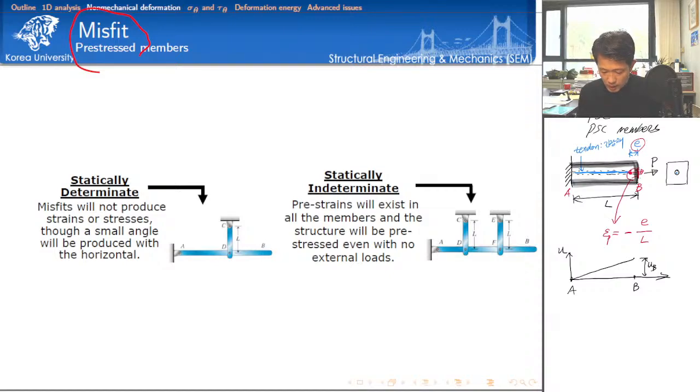Alright, now because we just designed the displacement field, the next step is to calculate the corresponding strain, isn't it? Here we have two different parts, the concrete and the tendon. But these two are in one piece, that's why the total strain should be the same. Total strain is UB divided by the length. As usual, this is nothing but the slope of the displacement field.